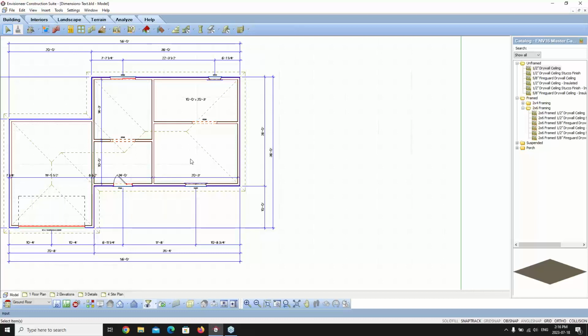You can also add text into your designs. So we're going to go in and select the text tools. The text can be added in either your model or your worksheet space to annotate the plan of the model. The elevation, sections, details, and 3D views must have text added once the view is inserted on a working drawing sheet. For the purposes of our exercise, we're just going to be working in our worksheets. So the text tool inserts strings of text to a worksheet.